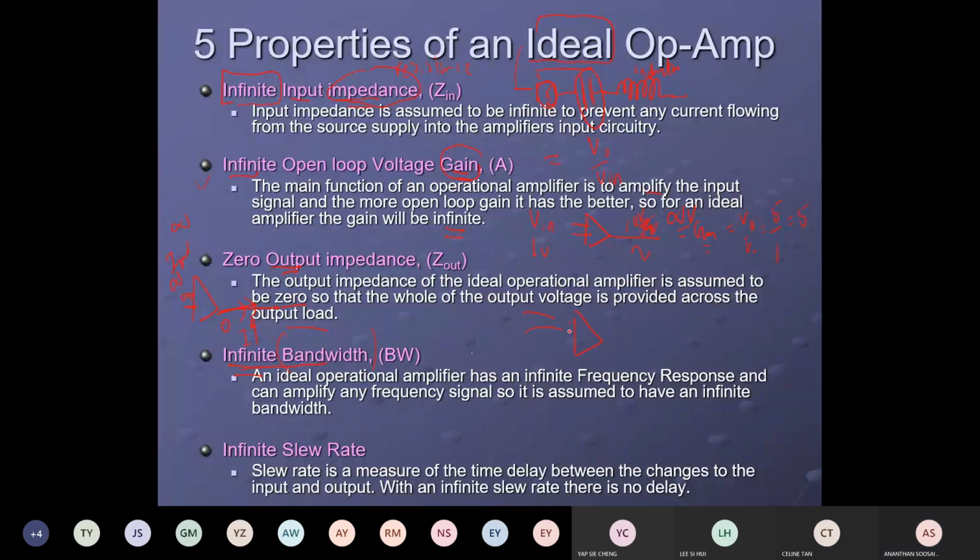If you give an operational amplifier a signal at a particular frequency, let's say 50,000 hertz, it will amplify the signal and make it bigger. But the op-amp has a certain bandwidth. Let's say its bandwidth is up to 50,000 hertz. If you give more than 50,000, what happens? The amplification won't be done properly. The amplification may be smaller. So the operational amplifier never works properly once it passes the range.